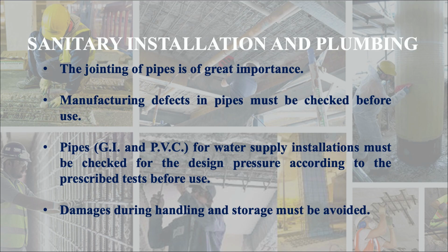As you know, there are many tests for testing of water supply pipes. These pipes should be checked for the design pressure, because if they fail to bear the design pressure, then they should not be used. They are not of standard quality, they are defective, if they are not capable of taking up the design pressure. Then damages during handling and storage must be avoided. These are also important damages that occur in the material.